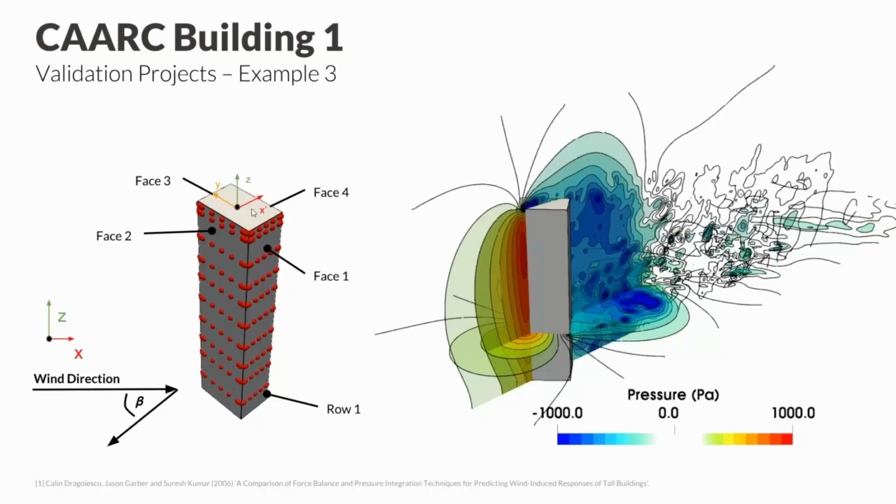measured. And on the right, you can see an arguably very fancy simulation of what we ran from it. So we ran this analysis with Pacefish, rotating this building, right? So running the wind from various angles and then measuring the moment it creates on the building and comparing that with wind tunnel data.